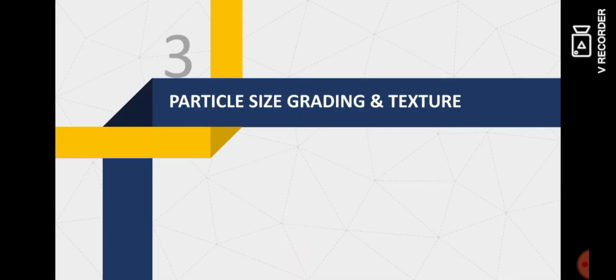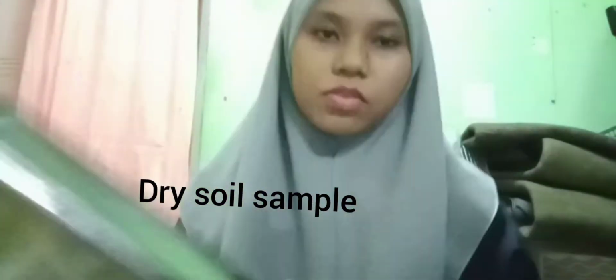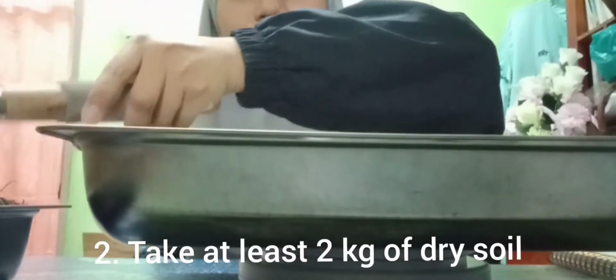Particle size grading and texture, I will show you the video of this experiment. For the particle size grading and texture, the apparatus is first sieve, 4 different sizes of sieve, and then weighing balance, then dry soil, and last metal tray. First, weigh the tray. After that, take at least 2 kg of dry soil.